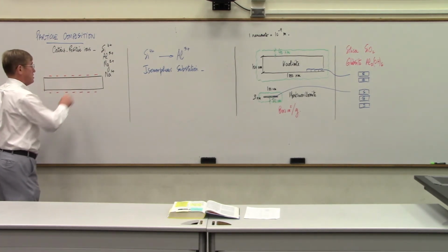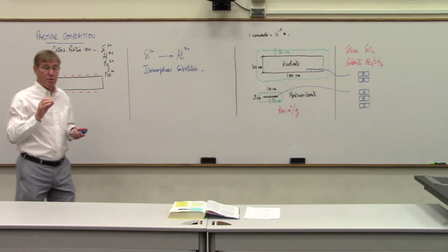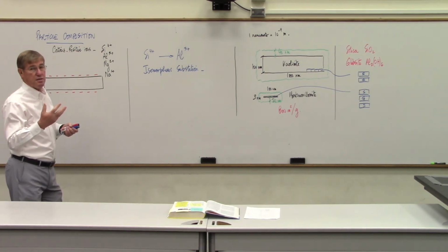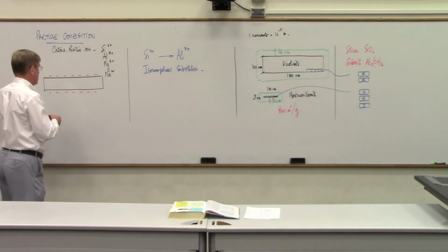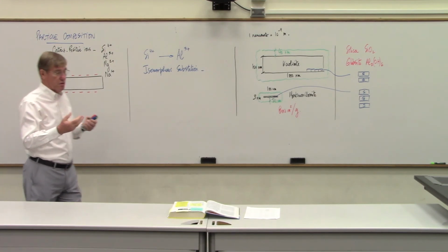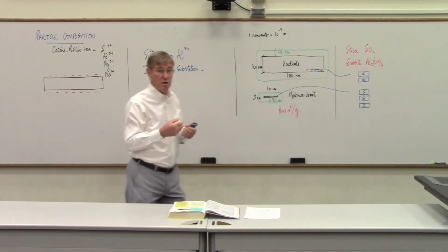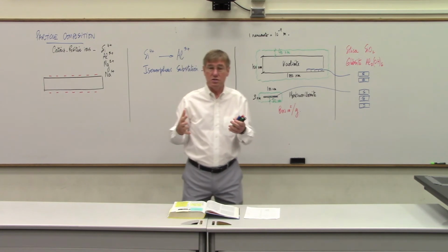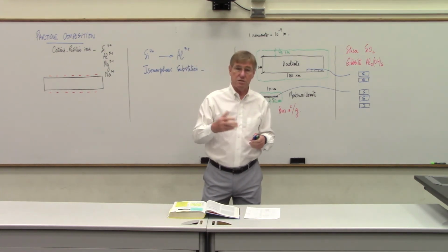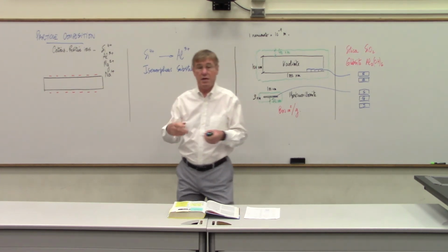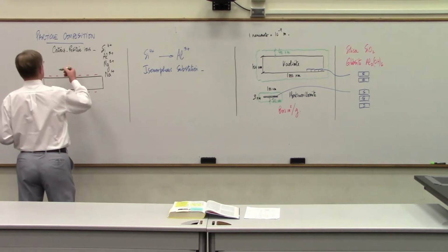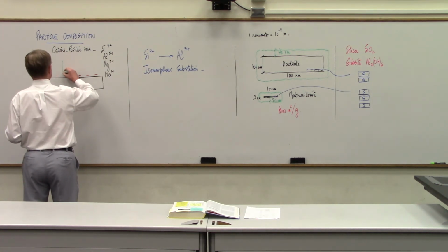Anyway, so we end up with a clay particle, which now is electrically deficient, and it forms negative charges on the surface. So because it has this negative charge, if there are some positive charges that are floating around, they're going to get on that particle and get stuck because of the electrical attraction. And these are typically the water dipoles.